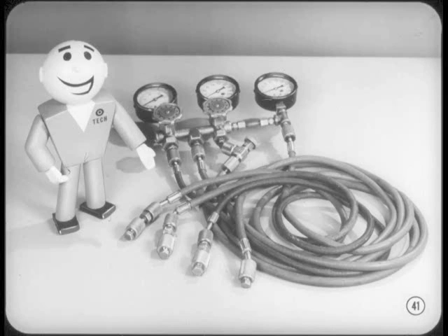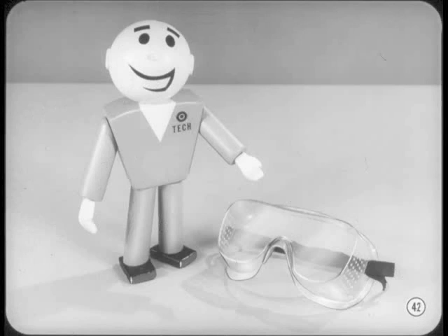When the gauges are not connected, it's a good practice to put plugs in the hose couplings to keep dirt and moisture out. Also, make a habit of keeping both gauge manifold valves closed to prevent accidental refrigerant discharge when the gauge set is connected. And to play it safe, remember that escaping refrigerant can freeze on contact. So wear goggles and also protect your hands when you open the refrigeration system for tests or servicing. Refrigerant does not damage painted surfaces, but will tarnish bright metal and chrome.